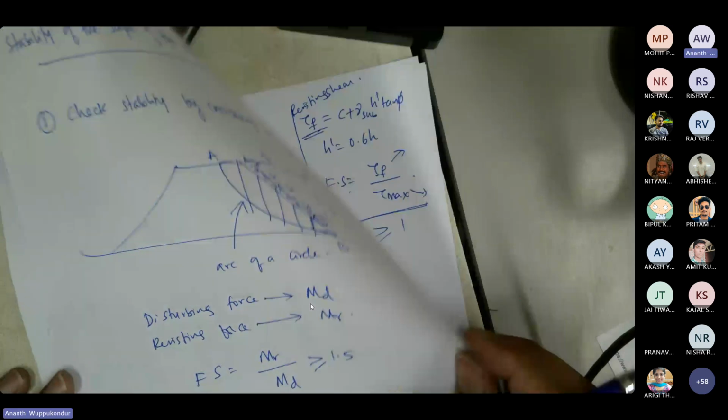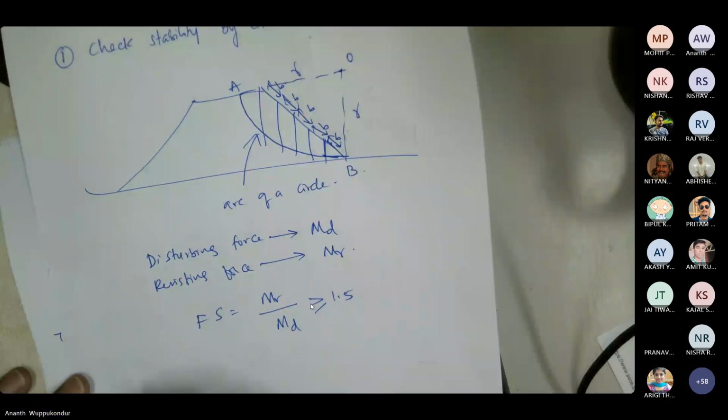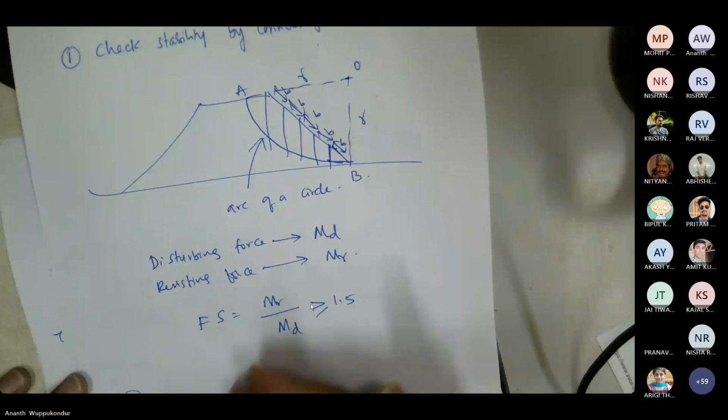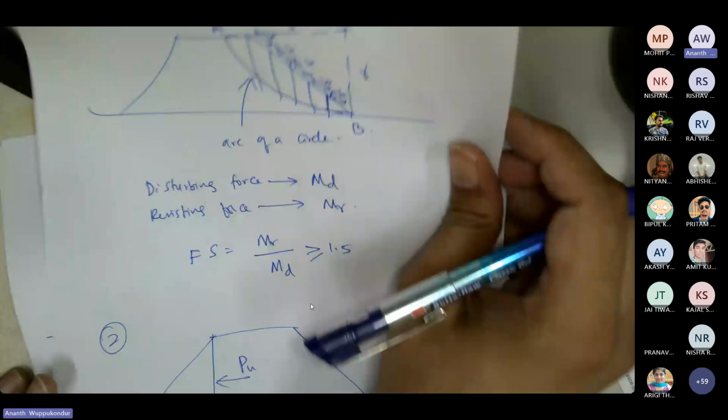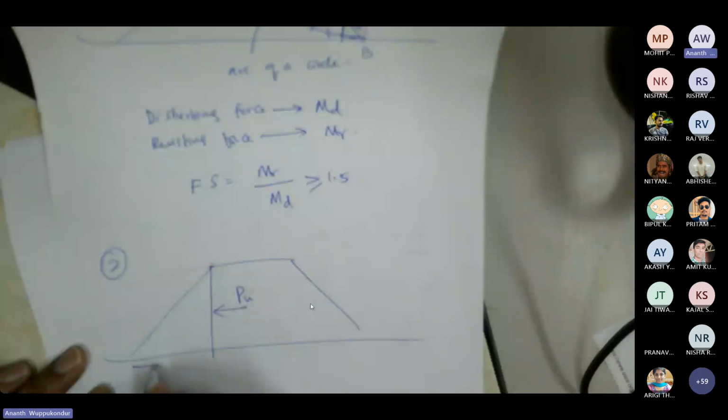And the second scenario for the failure of slopes is we consider a triangular section and try to calculate what is the horizontal force on it, which is trying to push this soil to the upstream, and this is being resisted by the shear stresses at the bottom.